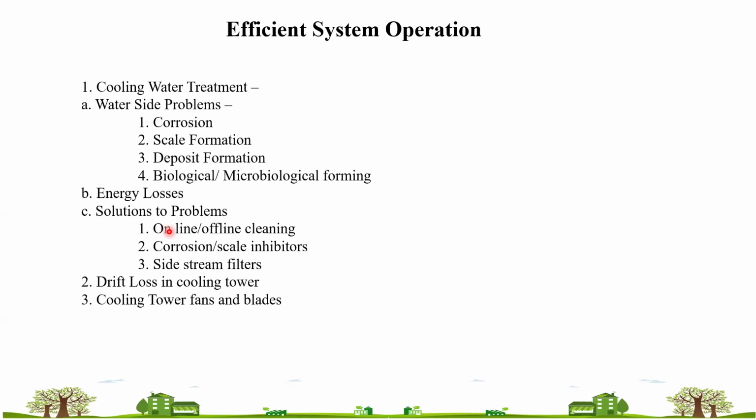Yeah. Okay. If you are doing a feedback based system, you have to set your feedback within the tolerable limit. Say your basin temperature is 28 degrees Celsius, and you are saying that at 29 degrees Celsius your fan must be put on.